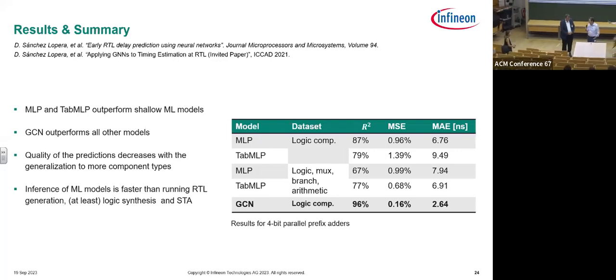I don't know if you guys have experiences with that, transferring timing predictions across technologies, for example. Nope. I would say no, it doesn't work, because we even have to redesign. We won't have the same core optimized, let's say, for 130 nanometer and for 22 nanometer. It's different because the fraction between area of cells and the runtime totally differs. It doesn't scale equally over the devices you use to build a thing.